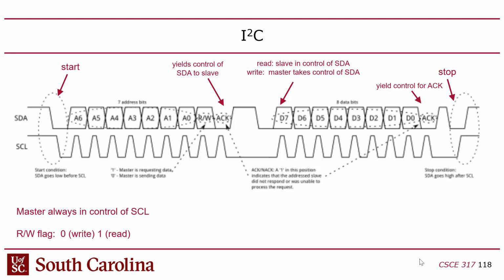Now remember, I said that you don't normally change the data when the clock is high, so when I want to start, I want to take mastership, I'm going to pull the data down while the clock is high. Now what's supposed to happen is, first of all, everyone's supposed to acknowledge that the bus is now being used by someone.